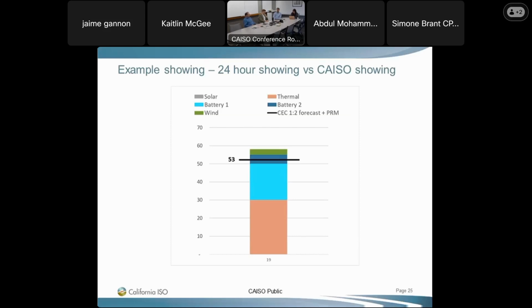I mean, this is sort of what Catalin was talking about earlier. What you're assuming here, Chris, is that this battery can actually dispatch 10 megawatts, right? Not 2.5. So if the PMAX is only 2.5, then you can't show it for 10 in 1 hour. It would depend. Right, but there are folks that build 10 megawatt interconnections and do a 1 hour battery. We have those. So it's not as simple as saying those don't exist and that they're capped at 2.5. No, yes, we're just clarifying that in that case, yes, it's fine. But it is only for 1 hour. The LSE still needs to get something else for the 23 hours, or they could spread it over more hours and spread other things over more hours as well. They have that flexibility.